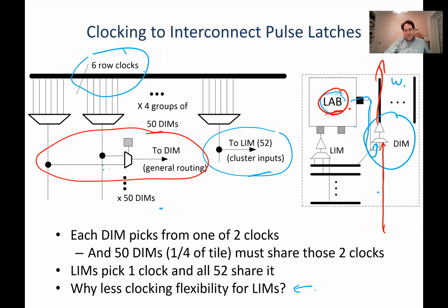Yeah, it's not catastrophic to just have one clock per logic block. So some FPGA architectures do say you only have one clock per logic block. Some will allow you to have two. I don't know of any that usually allow more than two. And you're right. The cases where you have two clocks in a logic block tend to be things like clock domain crossing FIFOs and so on. So there are some cases.